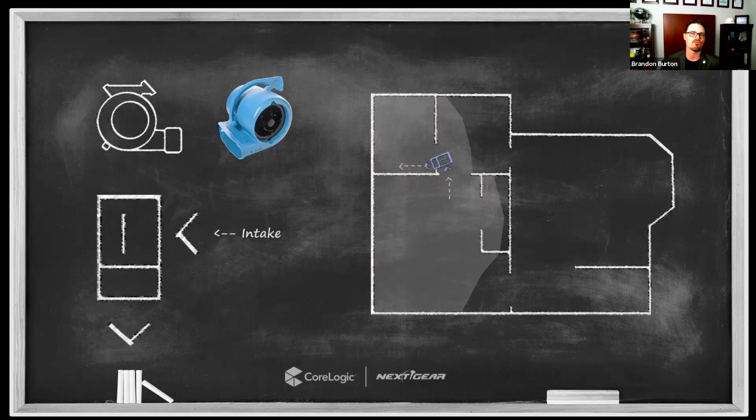That type of air mover is going to be installed at the opening between 2 adjoining affected spaces. There's a few of those openings between adjoining affected spaces in the schematic. I don't care which one you start with. Just pick an opening between 2 adjoining spaces. Now, notice what this air mover does. Its intake is drawing from the larger bedroom. Its exhaust is blowing into this, I don't know if it's a walk-in closet off of a bathroom, what that is, but it's drawing from one affected room and then exhausting that air into the next affected room or space.